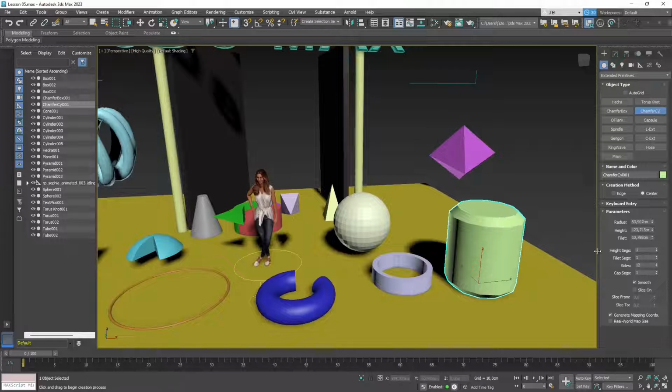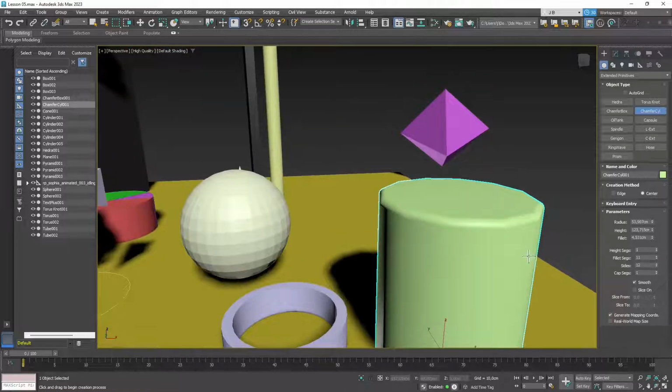You can also add just a single chamfer if you want, but if you increase the segments of the fillet right there, chamfer, fillet, rounded corner, call it how you want, you can do it straight or you can do it rounded if you increase the number of segments inside that rounded part. Now we also see some faces here.